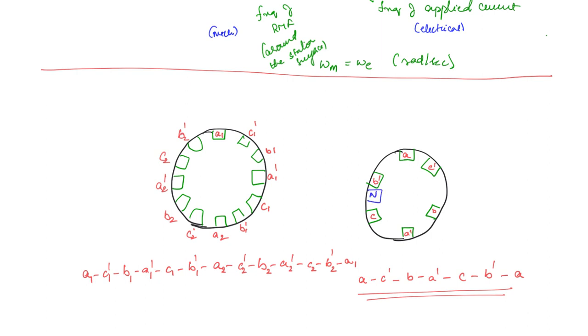Here you had only 2 poles. Here you're going to have, let's say this is where the north pole is present, and opposite to this you will have another north pole in 180 degrees. Here you're going to have a south pole, here a south pole. Now the position of these poles will depend on the time instant. Now in one electrical time period, what is going to happen? One electrical time period means the time period taken by the 3-phase electrical current. In that time, each pole will rotate only halfway through the stator surface. That means only 180 degrees.